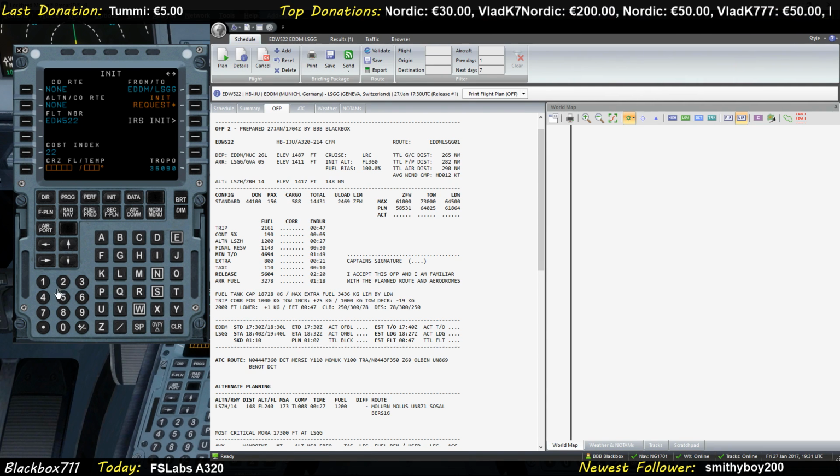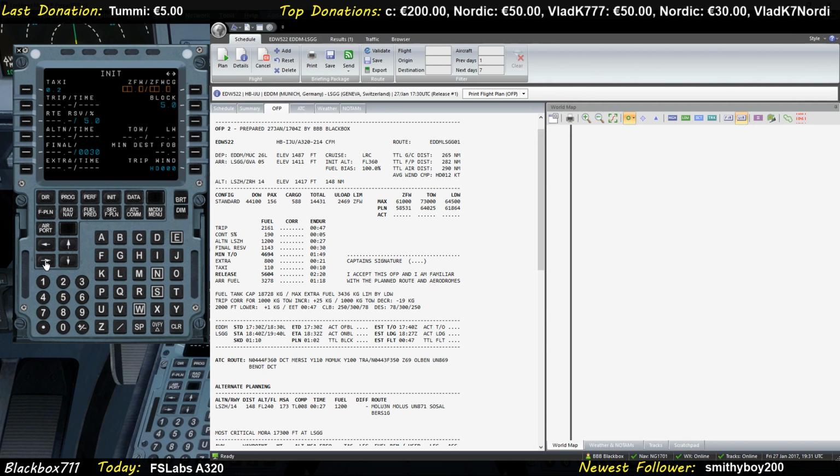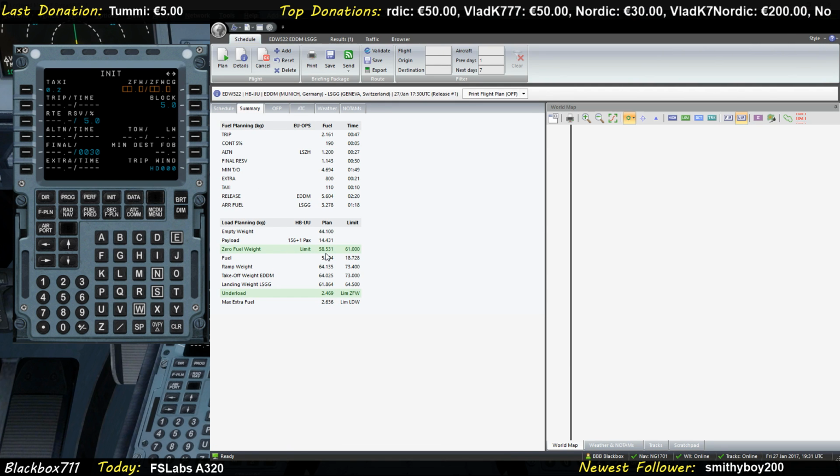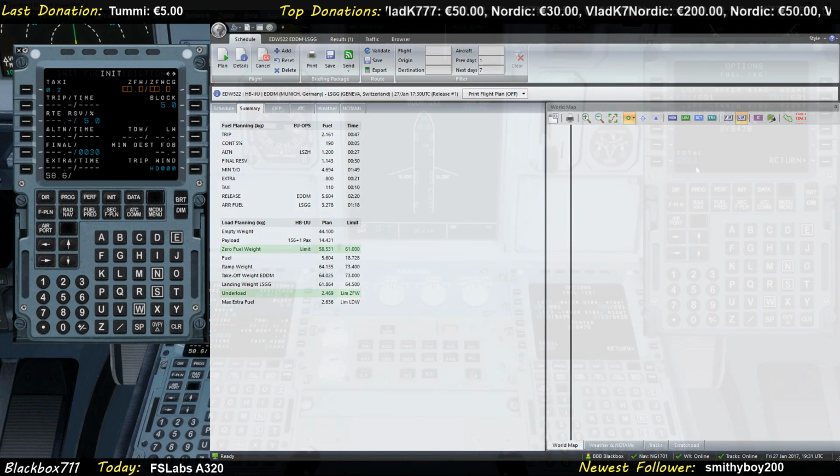Right, cost index 22. Cruising level: according to the flight plan, we have cruising level... where is it? Up here, 360. Zero fuel weight is 58.6. And the CG will get...